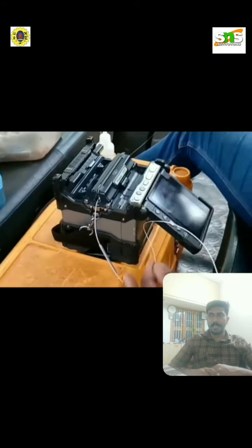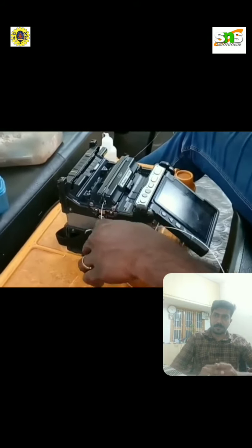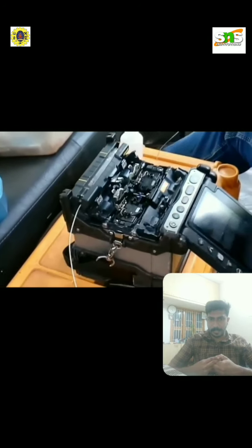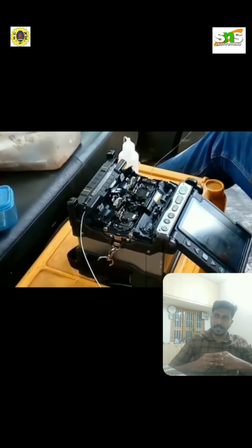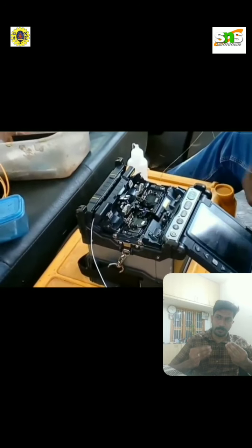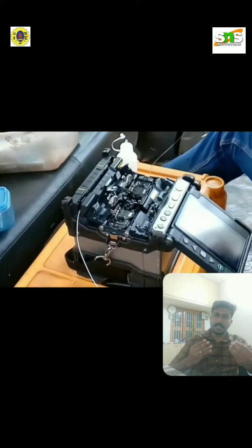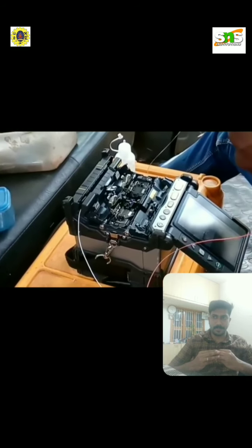And the fourth step is to protect the fiber. A typical fusion splice has a tensile strength between 0.5 and 1 lbs, and it is not easy to break during normal handling. However, it still requires protection from excessive bending and pulling forces. Using heat shrink tubing, silicone gel, or a mechanical crimp protector will keep the splice protected from outside elements as well as breakage.